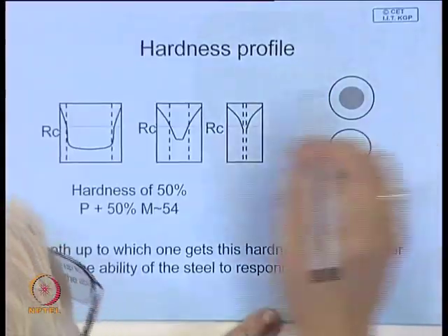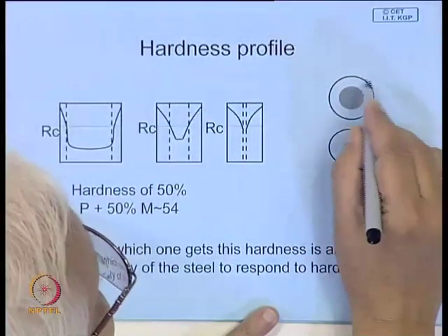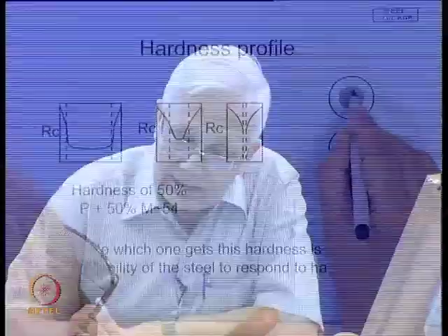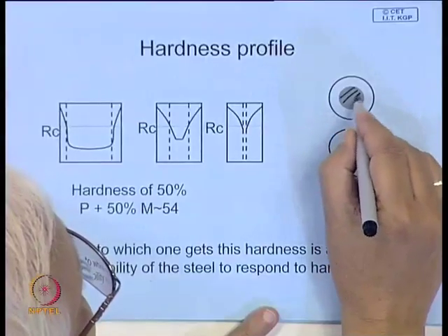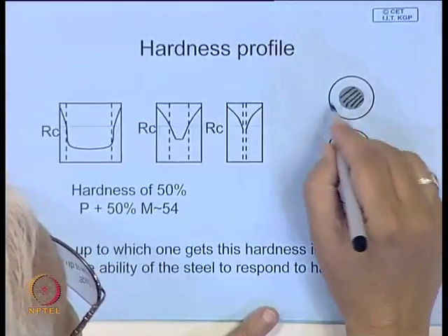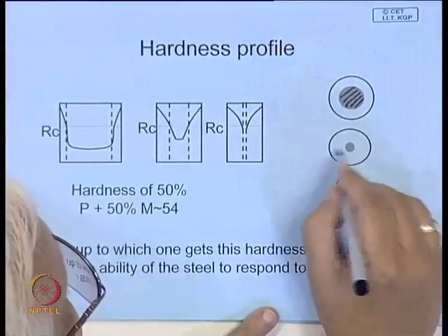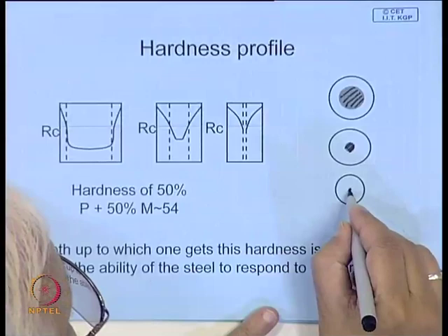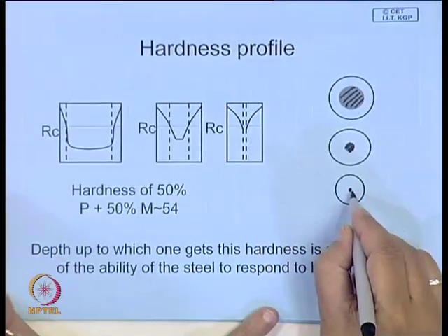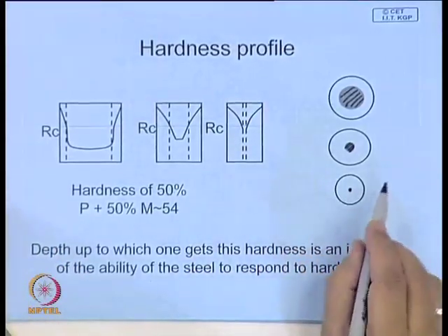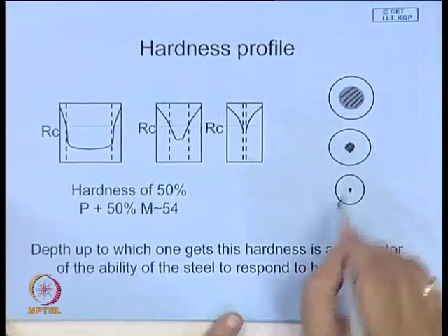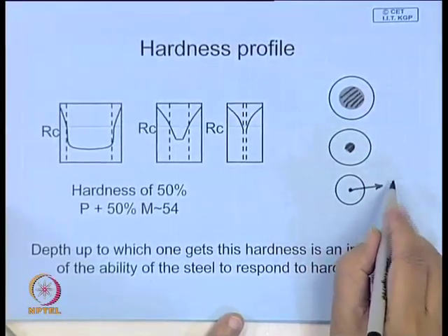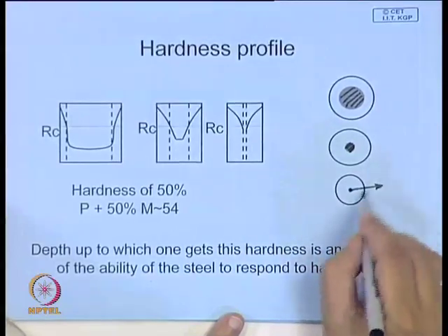You will find, suppose here, this is a little larger diameter, here you find that this is the portion where it is pearlitic structure, ferrite pearlite. If the job becomes smaller, you will find this is the size. If you make it still smaller, this. So in this way you can attempt to find out the diameter where this disappears. This just disappears.